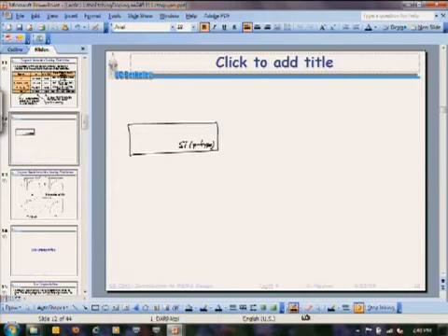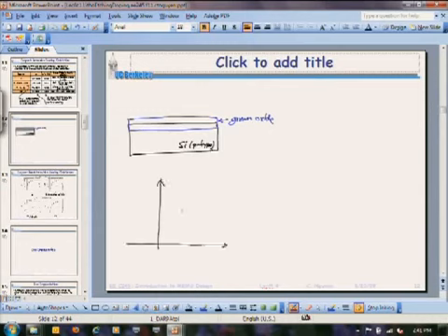Okay, so as that oxide grows, what happens to the boron in this oxide? And how can I tell what's going to happen to the boron? I mean, what happens to the boron at the surface of the silicon? What happens to the boron at the oxide interface? Okay, so what I want to do is plot concentration gradients here, sort of like what I did for gases. So this is oxide, that's silicon, and this is the oxide-silicon interface.